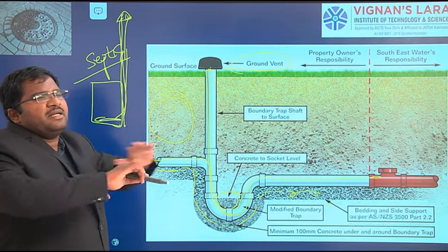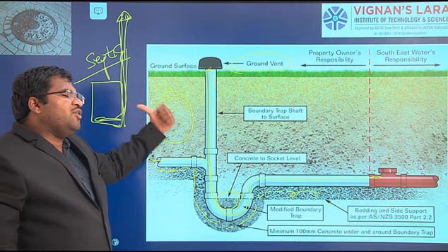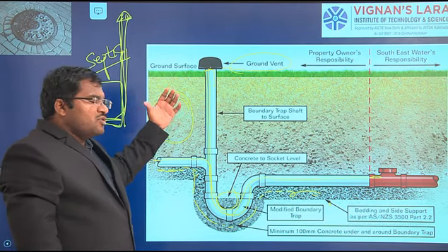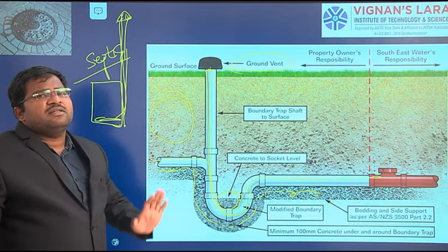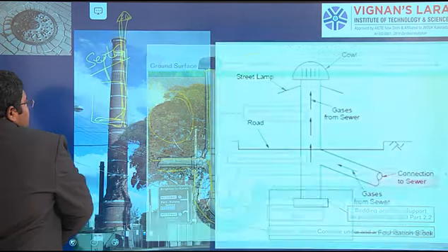What is the reason? That septic tank is completely closed, so there will be anaerobic condition. The same thing will occur here. So to remove those kinds of gases, vents will be provided. There also we provide them for safety. Okay, next we will see.